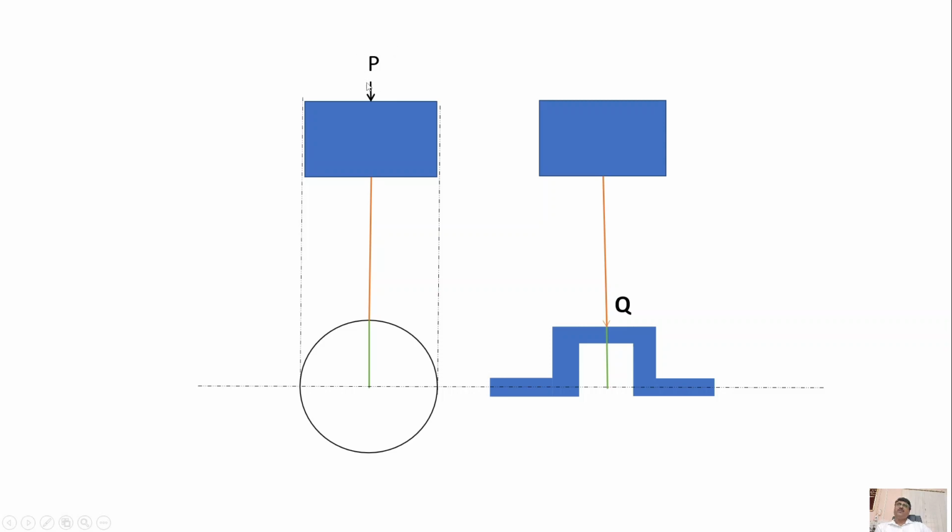The force acting on the piston will be maximum when the gas pressure on the piston will be maximum. That means when the gas pressure will be equal to Pmax, the force acting on the piston will be maximum, and at that stage the crankshaft component will be subjected to maximum bending moment.